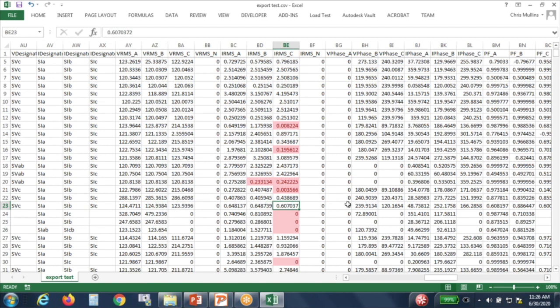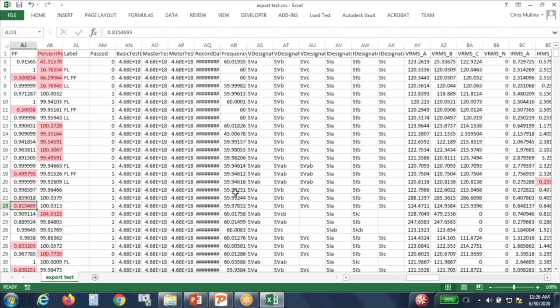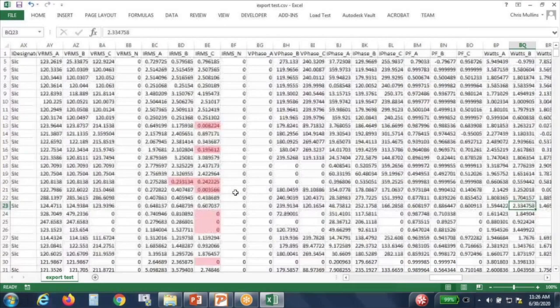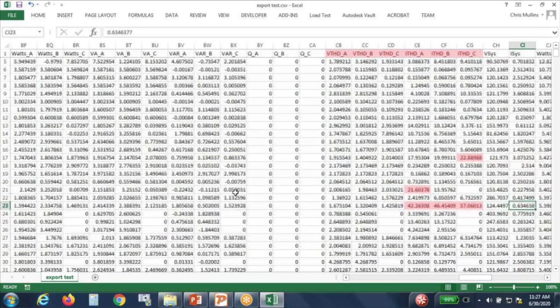Had a pretty low current, so about 0.6 amps on the secondary, and the registration was okay, but power factor wasn't so great. 0.8 power factor. Probably some kind of industrial load that was very capacitive, and so probably an idling motor would be my guess. That's in the facility that's causing that kind of distortion. Not that uncommon. So that was kind of the tools you can use.